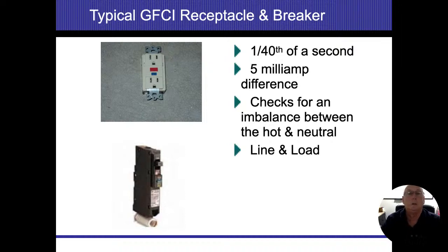All right. So I got a question. Did you cover wire sizing for grounding electrode conductors, either by rod or by water pipe? And the answer was yes, I did. So the GEC, whether it goes to a water pipe or to a ground rod, has to be a number 6 copper, and that's for under 150 amps, or a number 2 copper for 150 amps and over. So number 6 for under 150 amps, or number 2 if it's 150 or more.